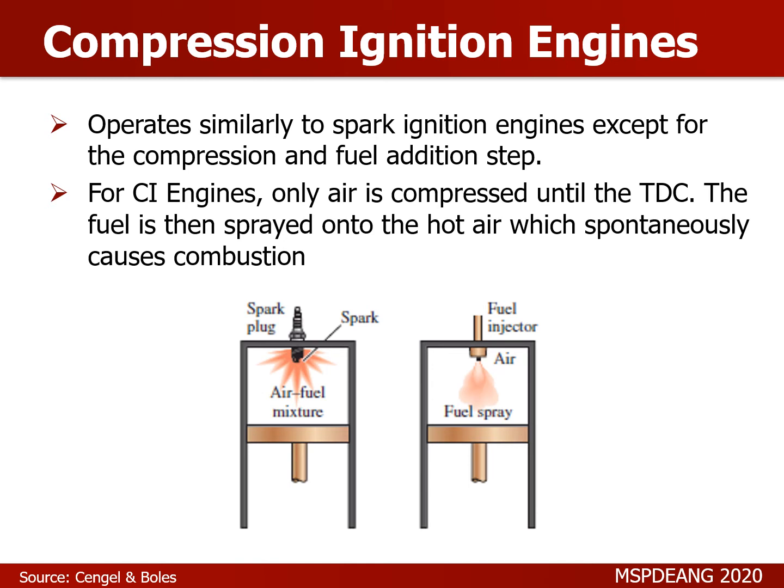So with this, unlike a spark ignition engine na literally spark mo yung air fuel mixture, for a compression ignition engine, you will now spray your fuel into the hot air. Therefore, this fuel sprayed mixture will now auto-ignite with the hot air gases. Okay, so okay lang na mataas ang compression ratio for your diesel engines kasi yung kinocompress mo wala siyang fuel. You only spray the fuel once you reach the topmost part of your stroke in your piston.